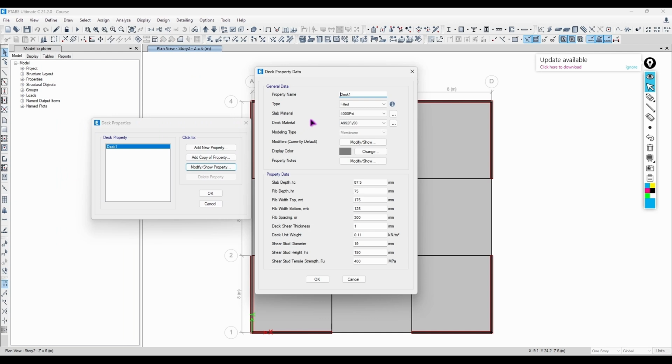If you can look here, a deck is technically, instead of using a wooden frame formwork, you're going to have a steel staggered kind of deck like this, and you're going to pour your concrete on top. So the concrete is going to look something like this after you're finished, right? All of this is concrete, and this is your steel deck, and the reinforcement is going to be something like this. And if the thickness is relatively larger than 160, you're going to have some reinforcement on top as well, right? And you can add confinement like this, or you can add studs as well, like shear studs.